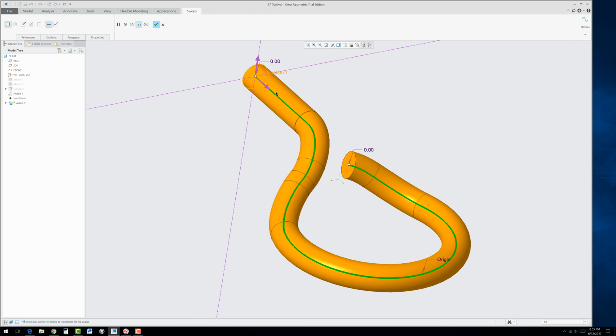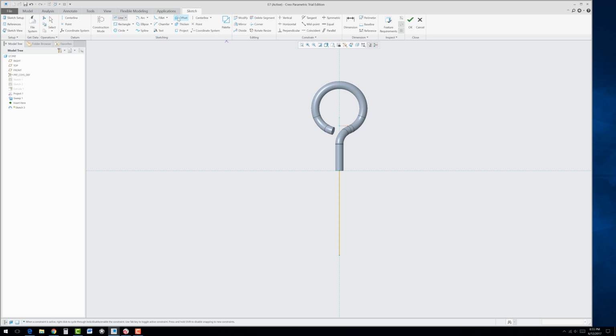Okay, so let's go ahead and now select the front plane, and we're going to just start a sketch on it. Now again, it rotated it the way I don't usually like, so feel free to click on Saved Orientations and just go to front so we all look like we're on the same plane, even though we were to begin with. But go to Line, and right at the bottom there, click and drag down a line, middle click. Now go to the Arc Tools, hit the little arrow to the right and find Tangent End Arc.